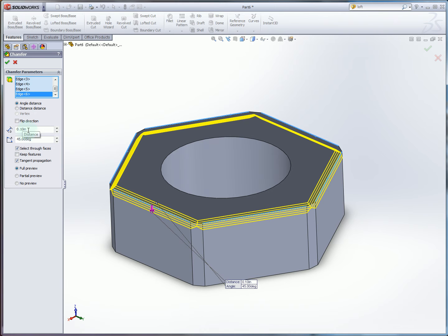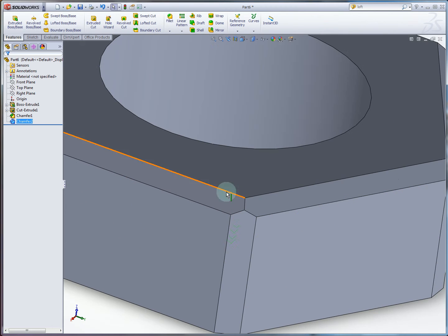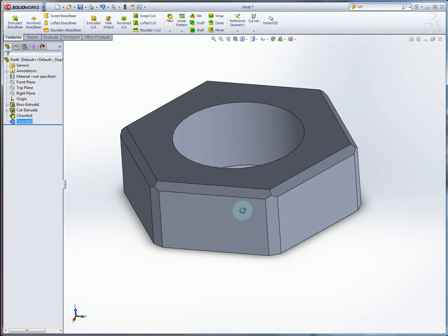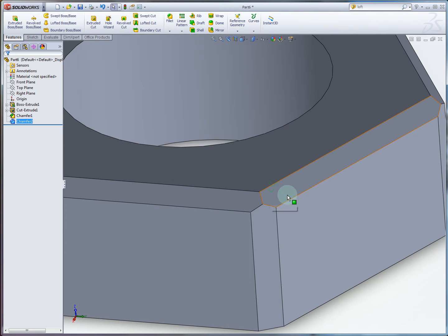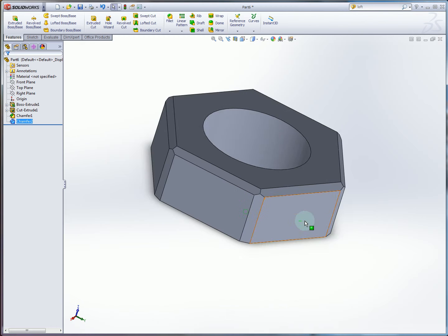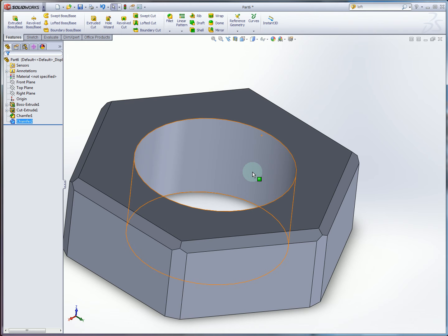So using that same setting here for thickness, 0.1 inch, and here since I'm doing perpendicular edges, I can get away with 45 degrees. I can apply this top chamfer, and now we have this nice uniform meeting of these three chamfered edges. So generally when you have chamfered edges coming together, this is what you want to see. Symmetry, uniformity, and it looks about like what you'd expect if you hand filed this part.